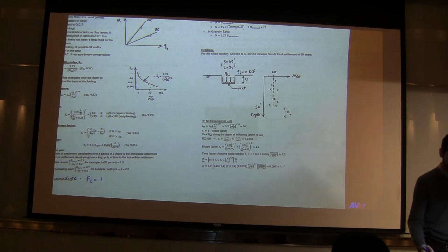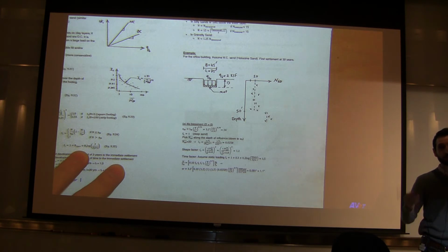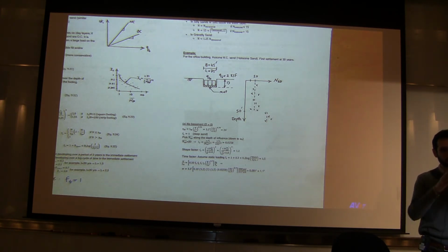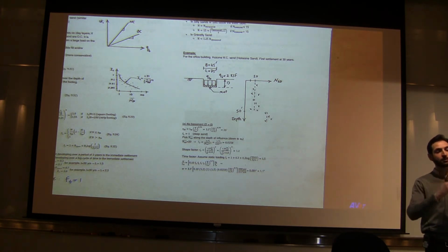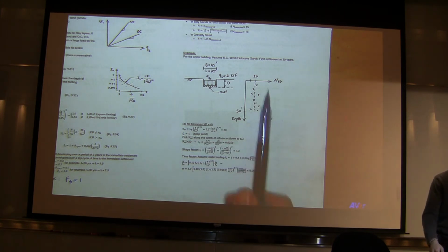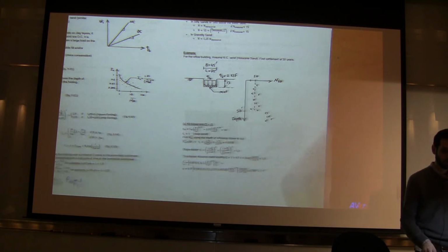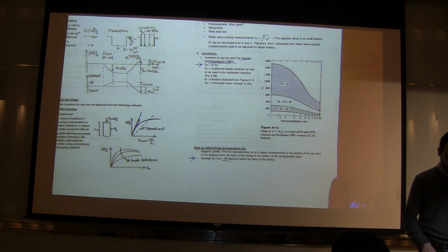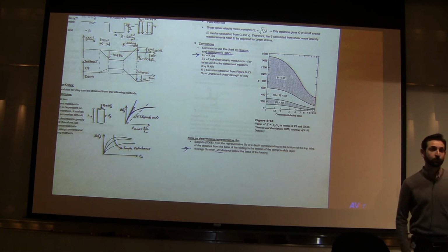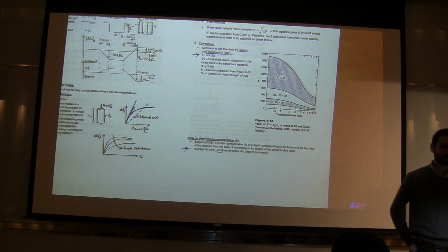For sand too, in this example N60 was kind of constant, but in reality, as you've probably seen in the other examples that we had in the problem, N60 increases. So if you assume a larger depth of influence, you're going to average a whole bunch of large values at depth, and that will increase your N60, that will reduce your I sub C, and that will reduce your settlement. Same thing with clays. If you average it over a larger depth, you're going to get larger SU, that will give you larger EU, and that will give you smaller settlement. So you have to pick something that is reasonable.